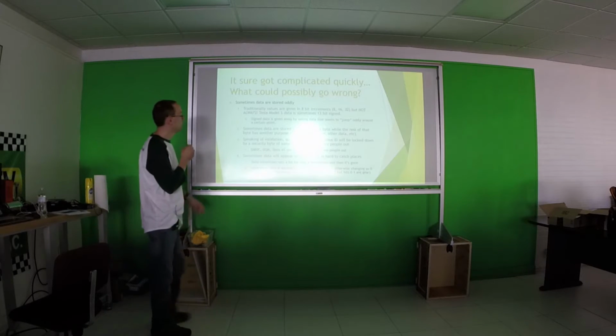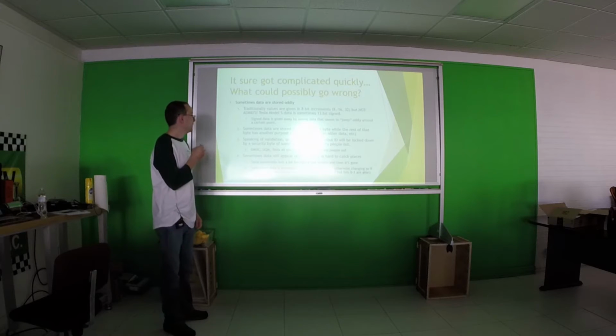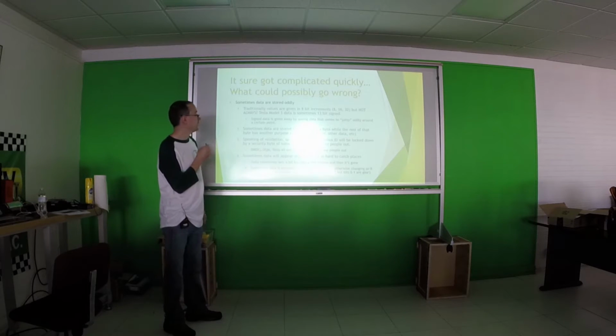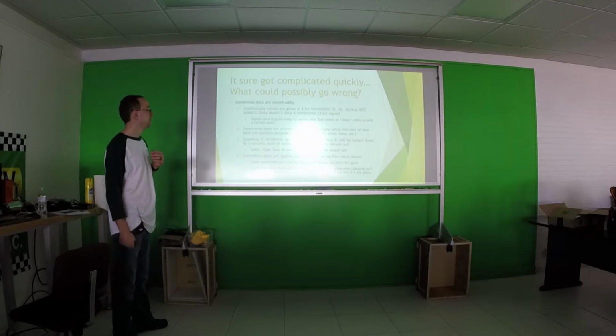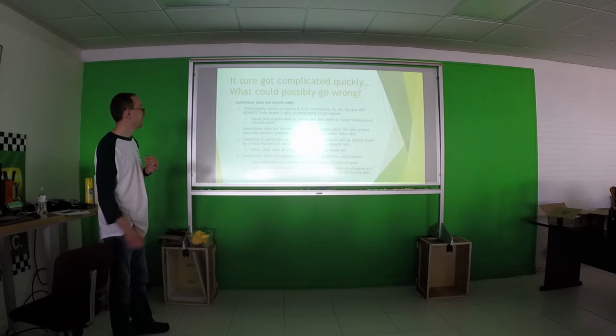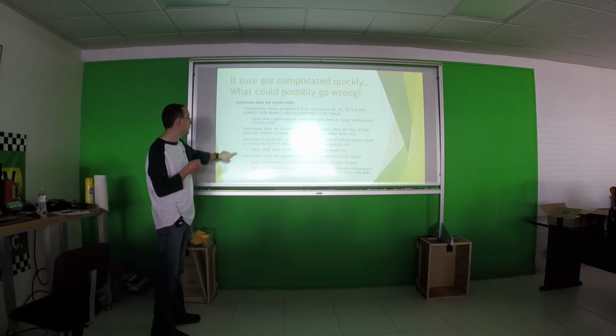Quite often, and this is one of the things my previous year's presentation was on, the UQM security byte. A lot of times Tesla has this as well. What they will do is the end byte. When you have an 8-byte frame, the end byte will be a security byte that is encoded based on the first 7. So sometimes you have to crack that, and that's kind of complicated to do, but my previous year we kind of covered that.